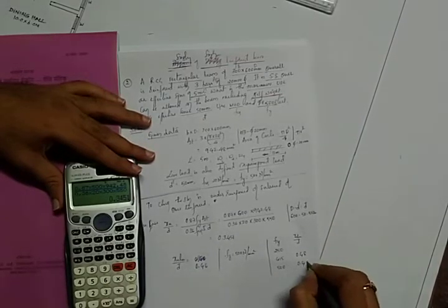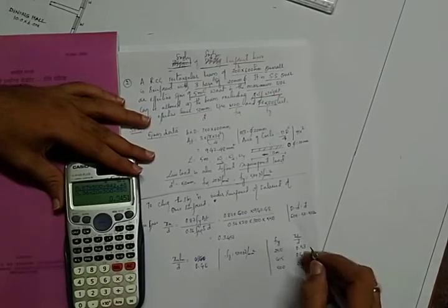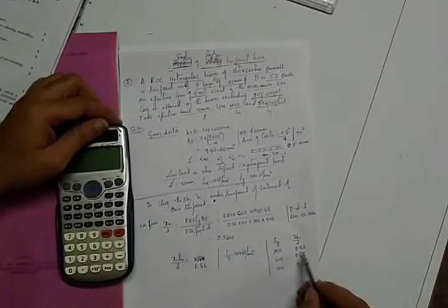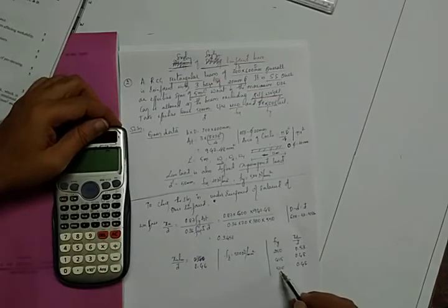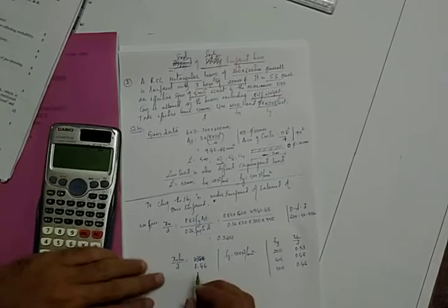So this is 0.46 and this, I hope, will be 0.53. We'll check once what is the value for that. Okay, fine. This is correct: for 250, 0.53; for 415, 0.48; for 500, 0.46. Then Xu limit by d is equal to 0.46.